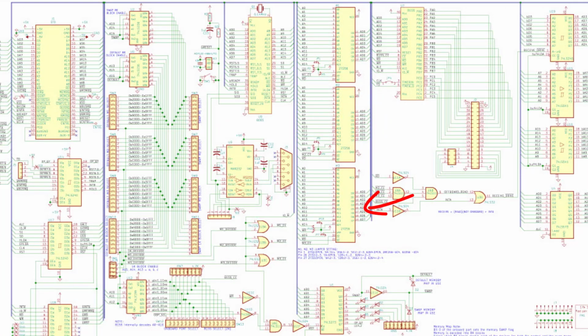Now, as a refresher, on this board we have 3 memory devices, M1, M2, and M3, and there's 2 memory maps. So we have an onboard port, and if we just change a bit in that onboard port, we can flip between the configurations of the default map and the alternate map. And with those 2 memory maps, each of these 3 memory devices, as well as the 8155 and the onboard port, is designed so that they can be selected from an address block anywhere within that 64K memory space.